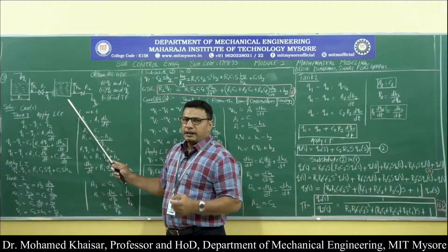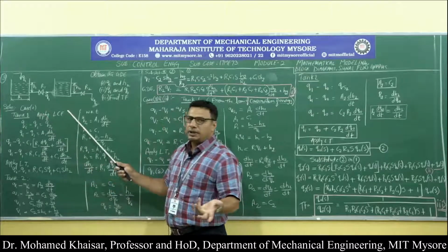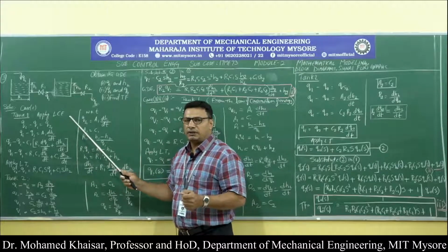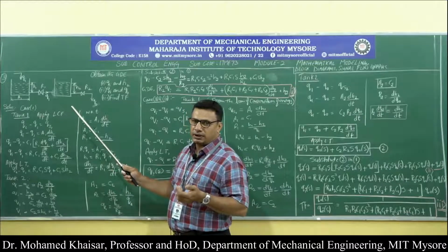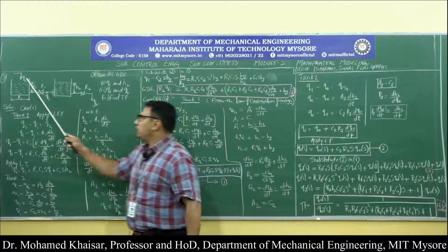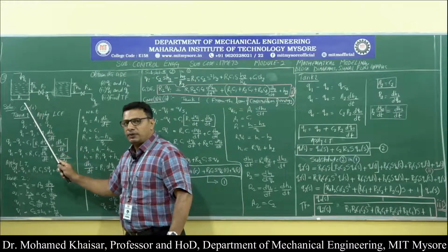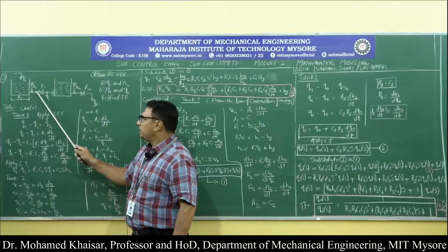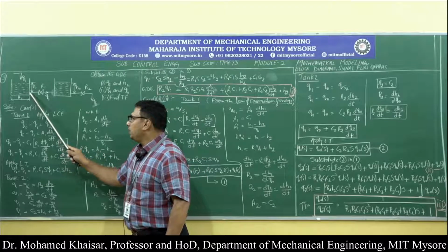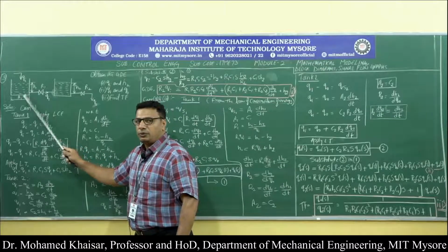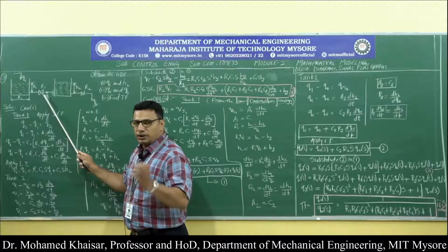You can keep that in mind, and just see what will be the transfer function of such a liquid level system wherein 2 tanks are placed in line with one another, and the inflow to tank 1 is qi. Tank 1 has the surface area A1 and the head is H1, and the liquid is discharged from tank 1 through the control valve, which shows a resistance.